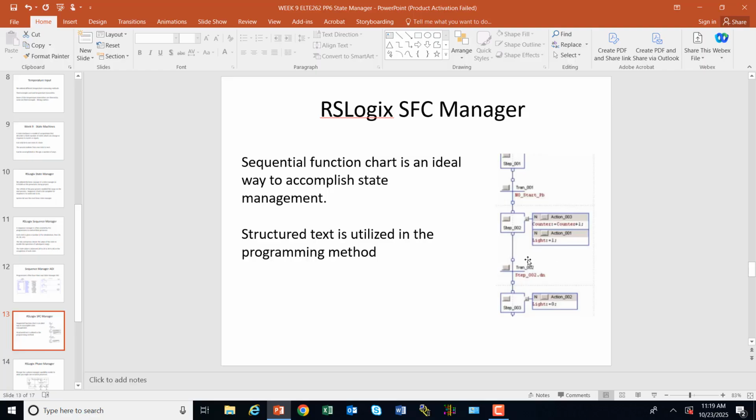I did want to get into some structured text this time a little bit, and sequential function charts are a great way to do it, but it doesn't need to be. You could build a little state machine straight away with structured text if you wanted to, and it's basically: if your state is equal to 1, then light 1 on, and then run your stuff. Then if state is equal to 2, light 2 on, whatever.